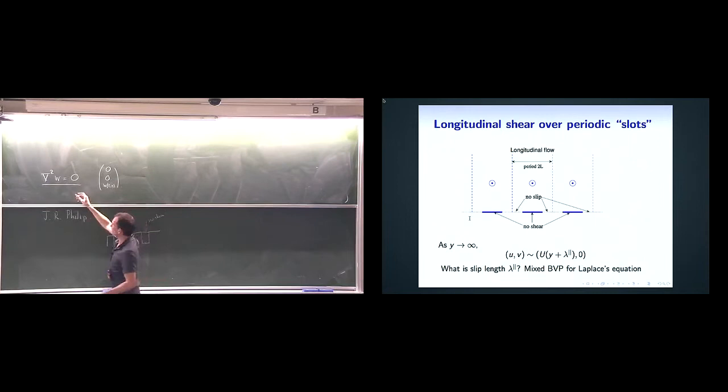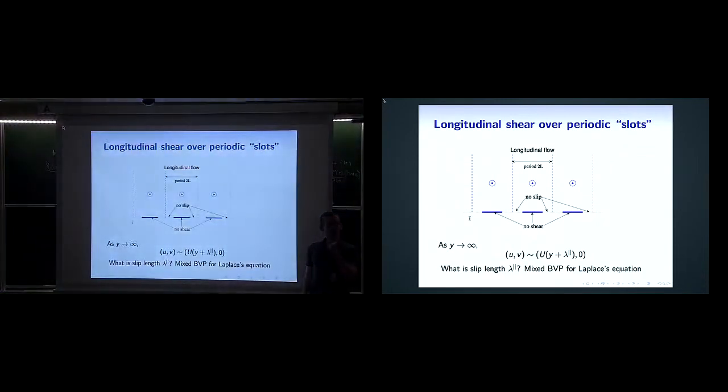If there's no pressure gradient, I think in my notes I have P, I think I have that. But if there's no pressure gradient, that's not there, and you're solving for a harmonic W, and so you can introduce what I called H, which is chi, which hasn't got a physical significance, plus iW. So this is what we want, and this is its harmonic conjugate. Doesn't have any physical significance. But I'm looking for an analytic function. Okay? So in Philip's problem, to find the most general flow over this surface, I need to find F, G, and H, 3 analytic functions.